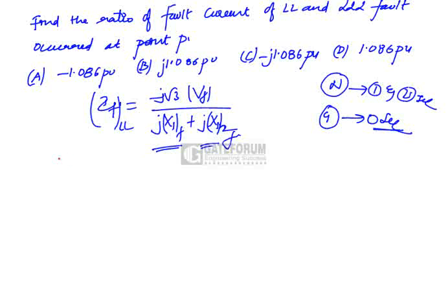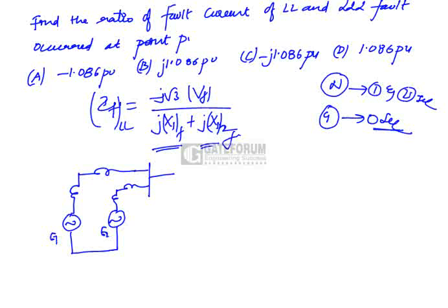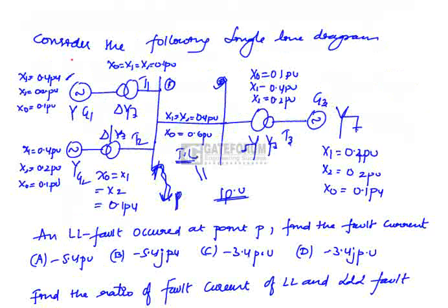Now what is the reactance diagram for positive sequence network is, okay, we have a generator G1. Active elements are represented as source in series with reactance, whereas static elements, or you can say passive, will be represented with respect to only reactances. Now this is generator 1 and generator 2. Let us take this is EMF E1, EMF induced E2. These are all dynamic equipment, so it is represented in series with reactance. So this is generator reactance. He has given positive sequence value as 0.4 per unit.